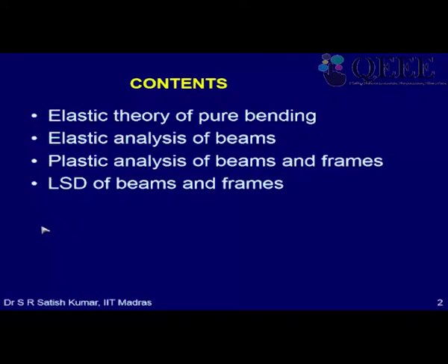First, we will look at the theory of pure bending. It's a very commonly used theory, and many of you would have learnt it in your strength of materials course also. But when you bring it to the design of beams, you have to understand some other issues related to it. Then we will proceed to elastic analysis of beams, where we will analyze some standard beams and work out the solutions, because I often find that people design beams without knowing the basic solutions and the implications of the end conditions, etc.